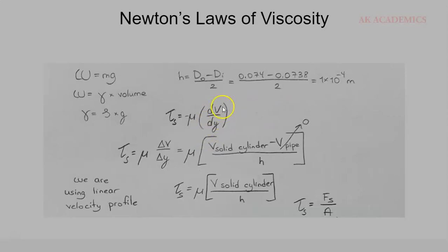So when we have these as limits, it simply means that this negative sign is just going to disappear because we are not going to use it for our calculations anymore. Once you represent this with the limit delta sign, and taking into account that we have some resistance because of the viscosity, eventually this becomes shear stress equal to mu, now the negative is not going to be there again because we're going to apply our mu now, and this time around it's going to be delta v over delta y, not just dv dy. It becomes delta v over delta y.